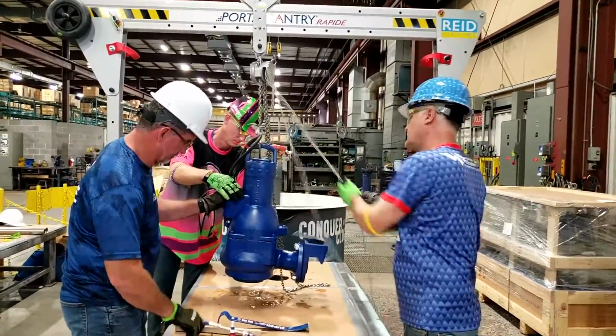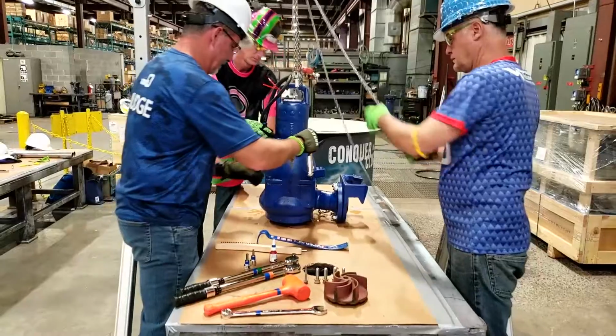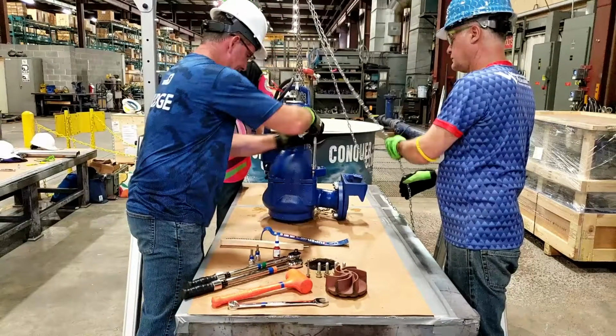For pump servicing, you may place the pump on its side or stand it back upright manually, provided the pump remains in contact with the table at all times. You may not manually lift or move the pump in a manner that causes the pump to lose contact with the table. You may use the gantry and hoist to lay the pump on its side or stand it back upright if you so desire. If you need to move the pump in such a manner that it will lose contact with the table, you must use the gantry and hoist.